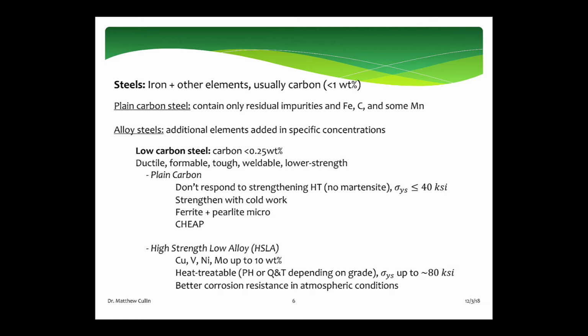Our alloy steels are generally going to have elements added in higher concentrations. So our low alloy plain carbon steels, except for manganese, we're not putting anything in there. It's just whatever's in there is residuals that we couldn't get rid of. It's essentially impurities.